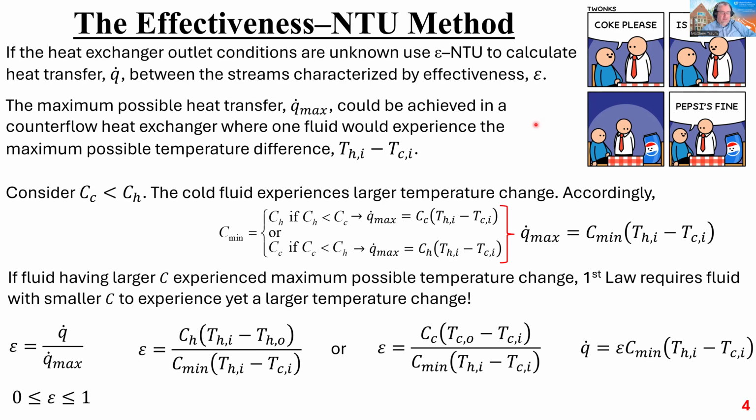But specifically for Effectiveness-NTU, I think it's important at least once to think through how it actually works rather than just blindly jumping in and using the technique. As you will see, there's some clever thinking built in here to extract information from the heat exchanger that you would not be able to get just by applying the first law of thermodynamics. If you think about which stream is doing what, which one has higher temperature and which one has more thermal capacity, you can extract additional information, which makes this technique viable.